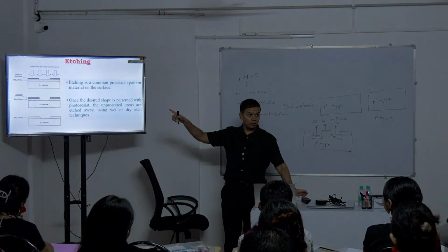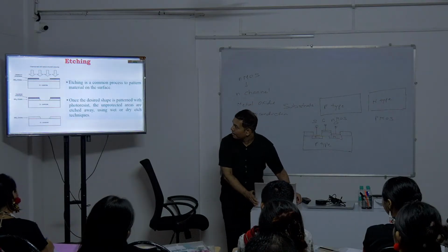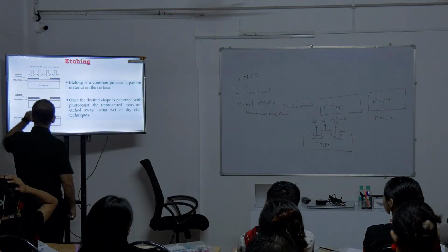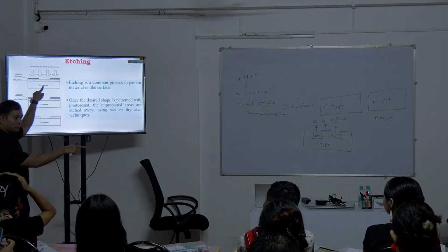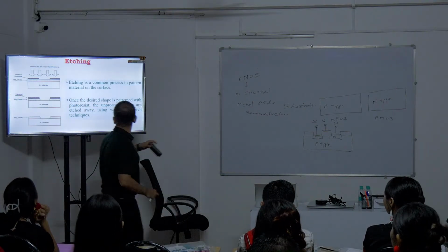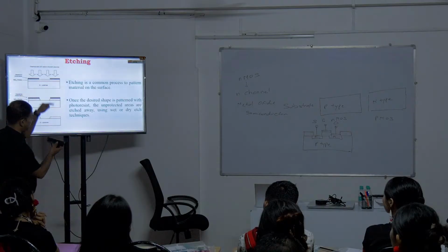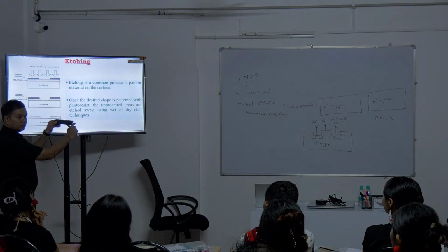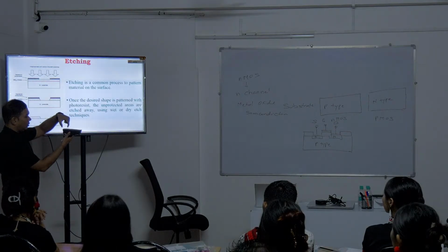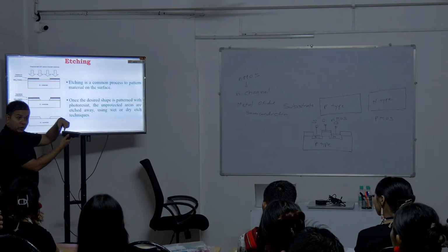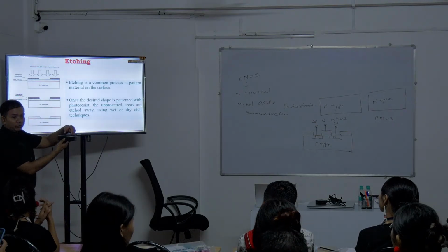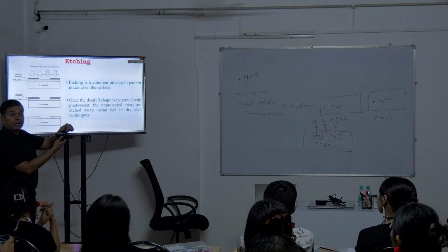Now understand over here what we are doing. So how to get this? Think about it. There's a black portion, and this layer is the white layer. Now what we are doing is, this is a photoresist. We put photoresist on top of the portion we need to keep, and the portion we want to remove, we are not going to put any layer on top of.